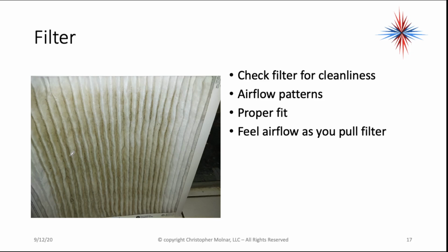Next thing, easy first. Keep it simple. Check the filter for cleanliness. Look for airflow patterns. Look for the proper fit. Feel the airflow as you pull the filter. If the system's running while you pull the filter out, you can feel how hard the air is pulling against that. Now, I have a relatively large filter in here.